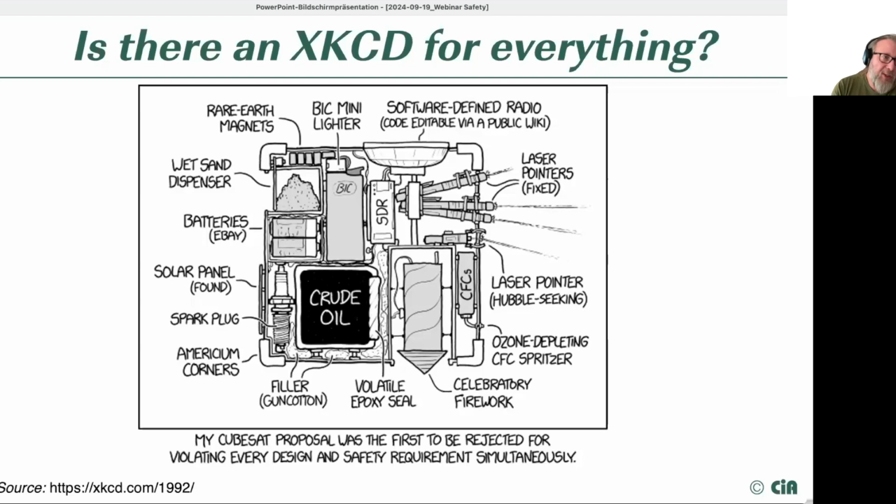The next question is, is it correct that risk assessment is mandatory for machine builders and not for suppliers of safety components? In general, the original machine directive and also the machine regulation is applying to the machine. So that means the risk assessment needs to be done for the machine, always for the complete system, for the complete machine.